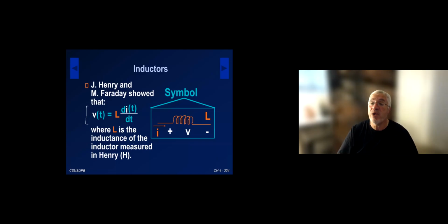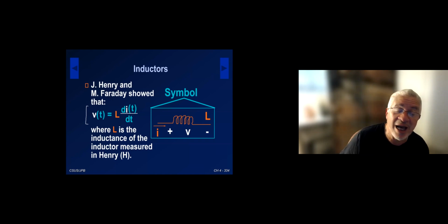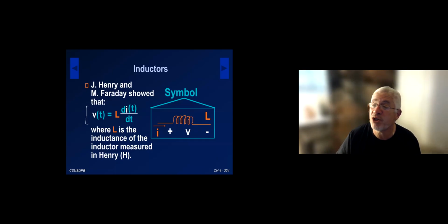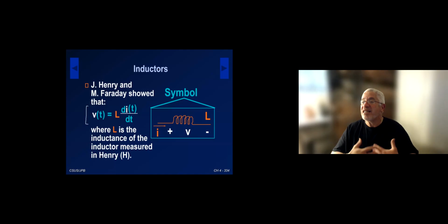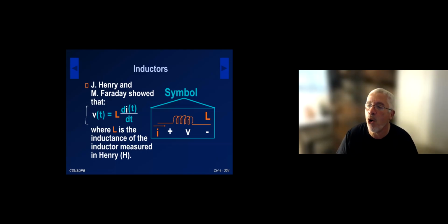And the reason we have that is because for an inductor, the voltage is related to the current by its time derivative. Okay, so V, and you can see what I'm starting to do here, I'm starting to write V as a function of time, because we're slowly going to have things that change, is equal to the inductance times the derivative of the current as a function of time. All right. The next lecture, I'm going to put them in circuits. Now, these circuits are going to be simple circuits. They're going to be circuits with DC sources, constant sources, but they're going to have switches that are switching them on or off.